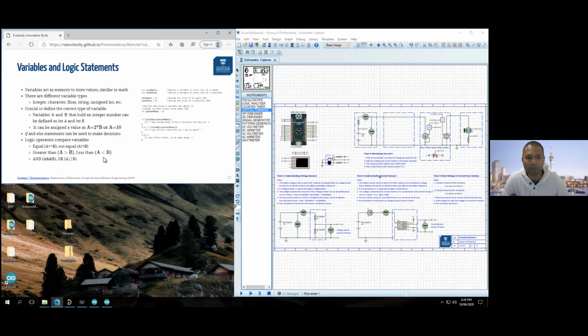And then you go into variables like floats that can hold decimals. I've done Python programming, so I have. Okay. Yeah, it's similar across most programming languages. In embedded programming, if you're defining an integer, you also have the flexibility to define it as an 8-bit, 16-bit or 24-bit integer, just because you're memory limited. You could play around with the size of the variables.